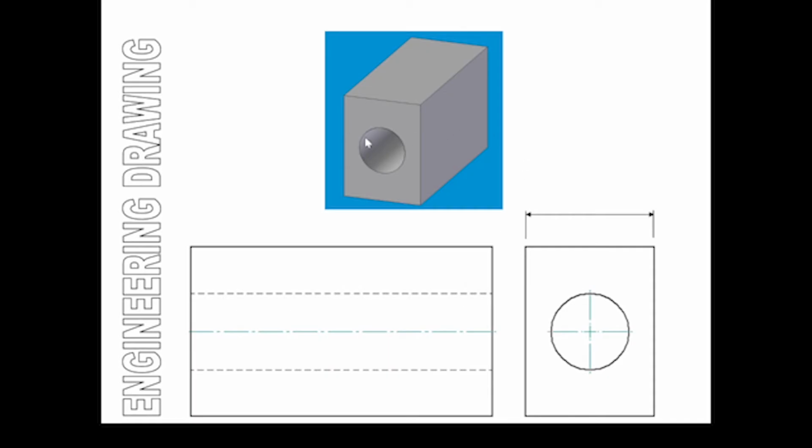So if you're looking at it sideways, you're obviously not going to see the fact that it's a circular cut. It could be a square cut or a rectangular cut looking at it sideways. When you look at it from the front, you're going to see a circle, and since it's a circular detail, you have to always support that with a crosshair-like symbol.